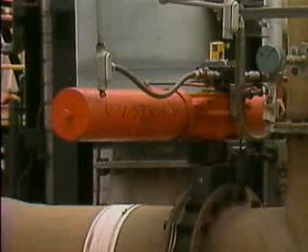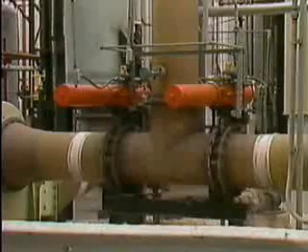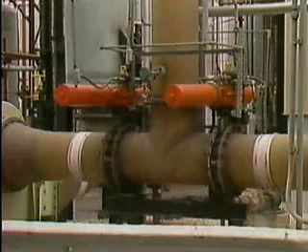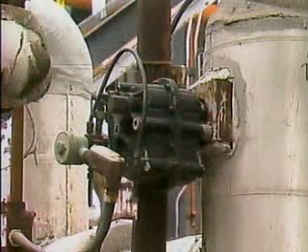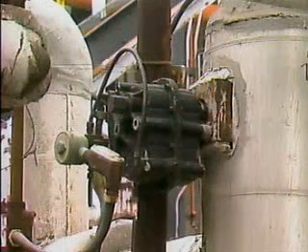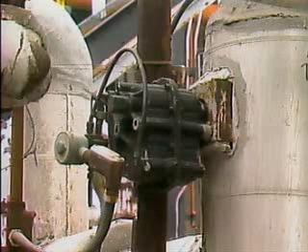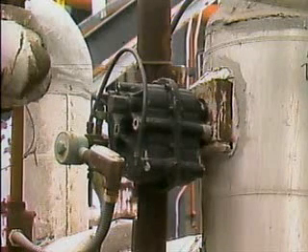The piston actuator is a pneumatic operator that uses a piston inside an airtight cylinder to position a valve. It's generally more suitable than a diaphragm actuator for jobs that require relatively long stem travel or more force to position a valve. The vane actuator is a pneumatic operator that uses air pressure against a vane or paddle to position a valve. This type of pneumatic operator is used primarily with ball, plug, and butterfly valves.